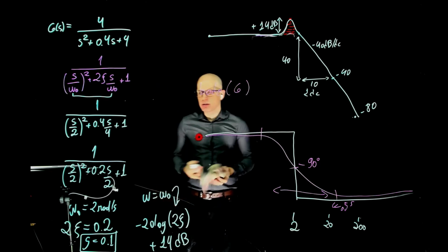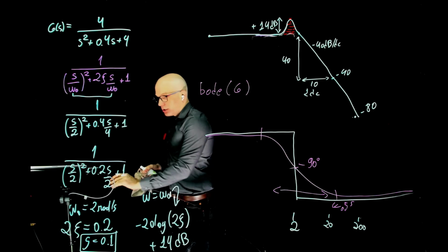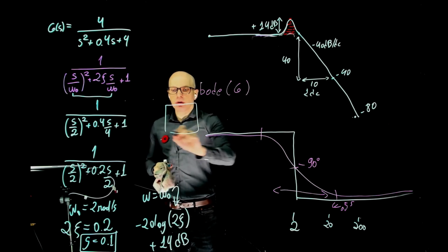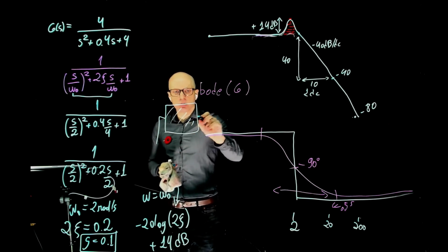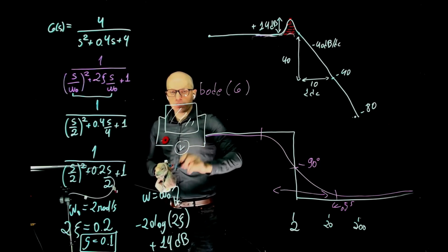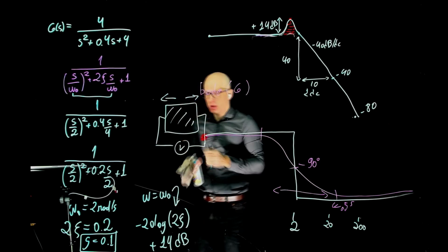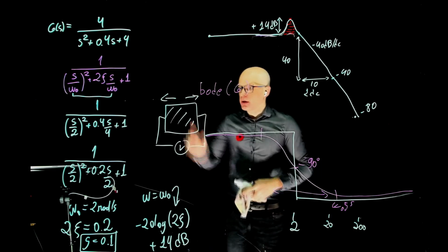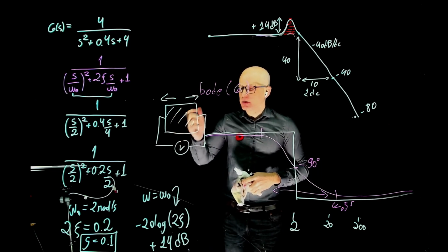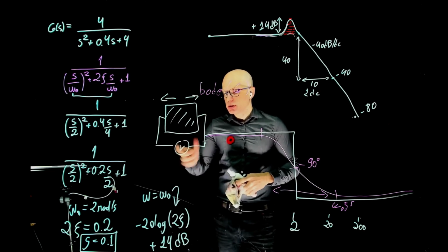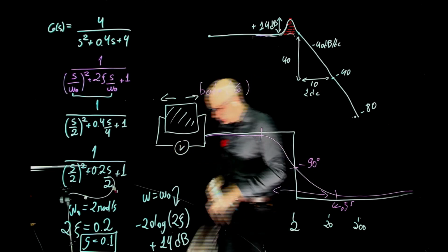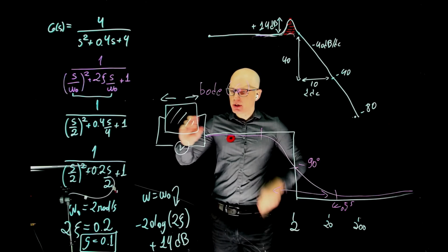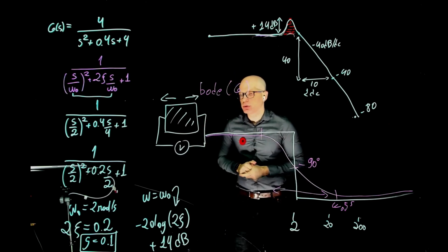So in some cases, for example, have you heard of piezoelectric actuators before? It's a crystal, a material like this, and you apply a voltage to it. When you apply a voltage, it will change shape. It will expand or contract, depending on the sign. And it can also work the other way. If you hit it with a hammer, for example, and you put a multimeter here, you will see a voltage showing up. This is typically the sort of actuation system that is in camera lenses. It's a piezoelectric actuator that deforms, and then it makes something rotate.